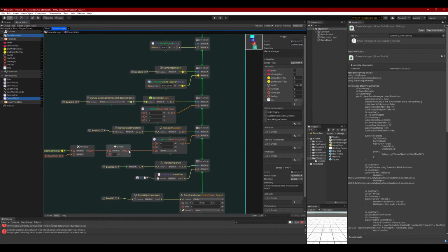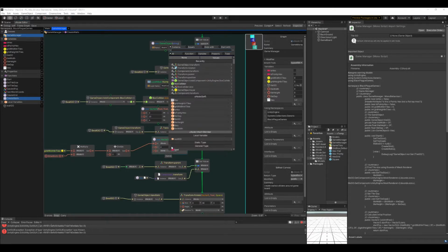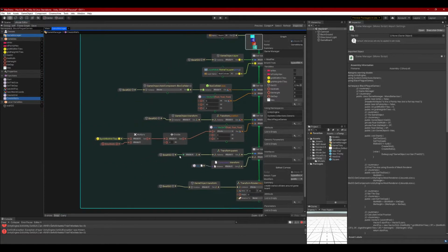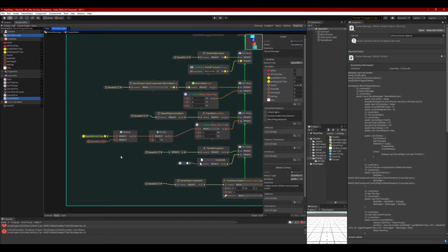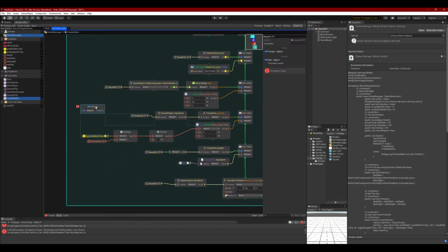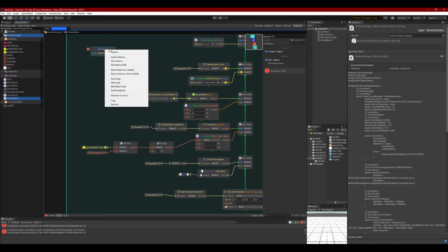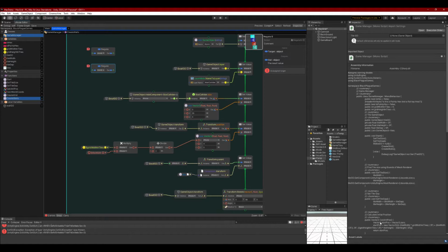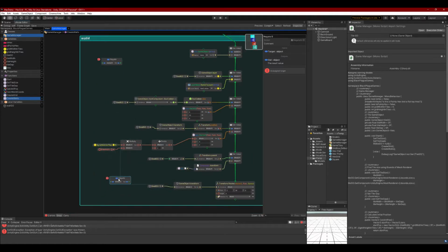So on wall 4 we just updated the name, and then we are relinking that to the x-axis and removing the link to the z-axis, and then also grabbing the float value and then keeping that as 0. For walls 3 and 4, we need to put a negate option. I did forget that, so we need to put a negate option for their position, so they're the opposite of walls 1 and 2.